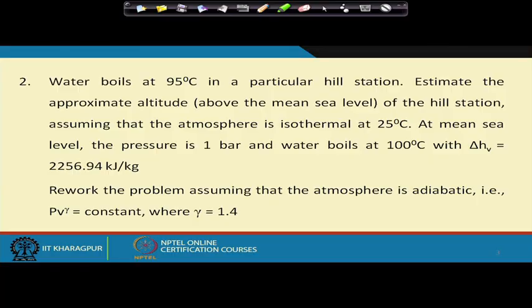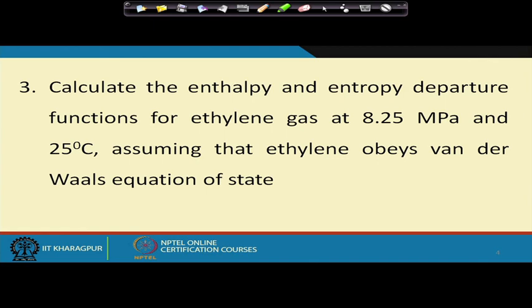So, now we go to the next problem. We had enough of Clausius-Clapeyron. So, at the moment we would go for some property estimations. Now, in this regard I would like to tell you that we have already discussed property estimations, and we found out that there are several equations, and when we do not know exactly which equation the gas obeys, then under that condition we either refer to the compressibility factor chart or we refer to the reduced coordinate charts which express delta H star and delta S star in terms of a unique function of reduced temperature and pressure. Now, mostly in industries we find that the charts are very much used, but it is difficult for us to provide charts etc.